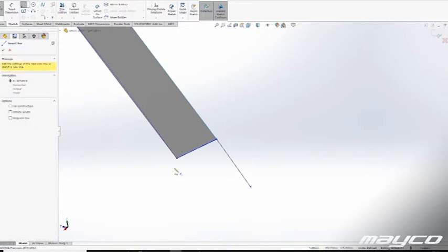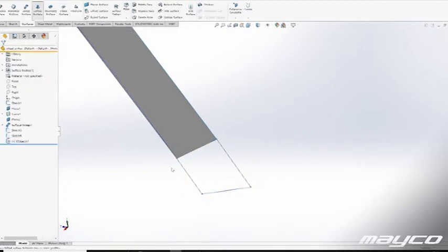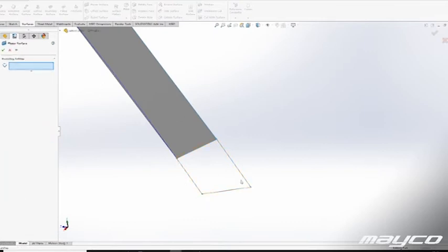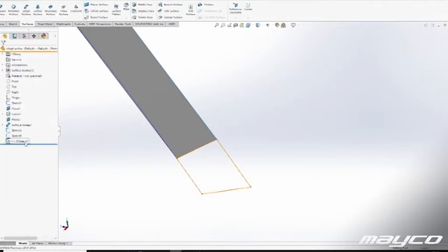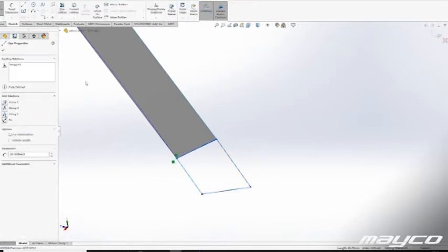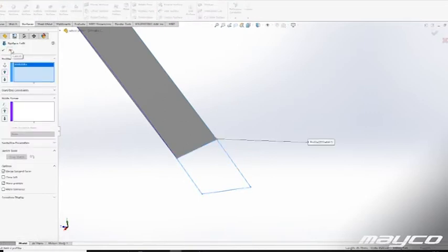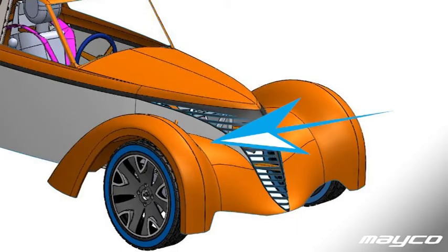What's important with this kind of wheel arch is that the suspension arms need to fit underneath these curves. On the outside, that's not really a big issue because the fender flares on the outside are very big, but towards the inside they are much smaller, and there it will be difficult.